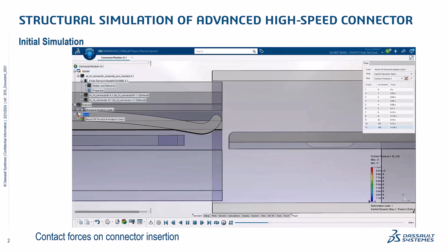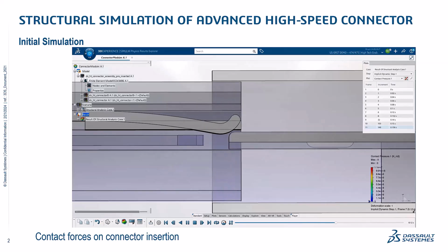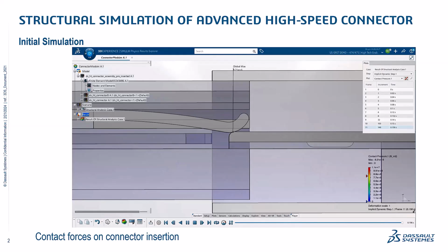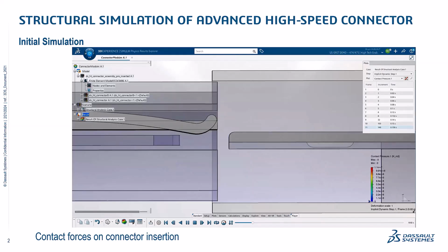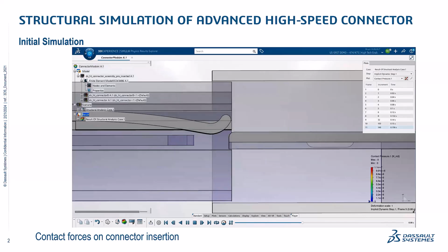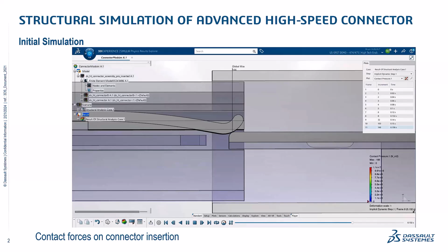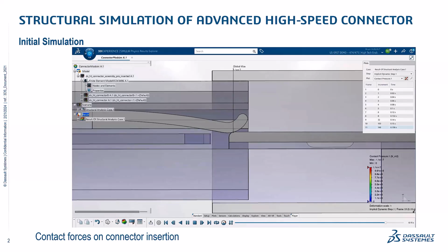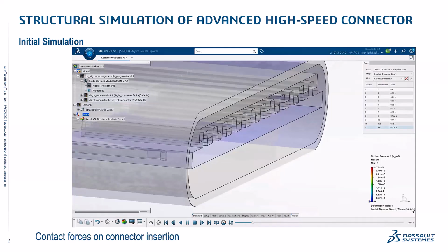All right, so using the same CAD model that David was using, generated from SOLIDWORKS, we can generate a finite element analysis model of the mechanical parts of the connector. That's what you're seeing here. This model begins with the connector unengaged, or disconnected, so that we can determine the final deformed configuration and stress state of the connector once it's plugged in or engaged.